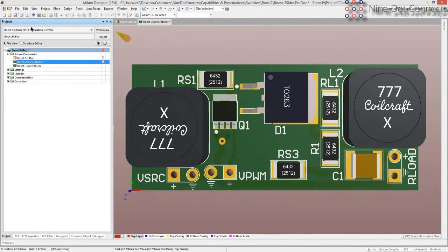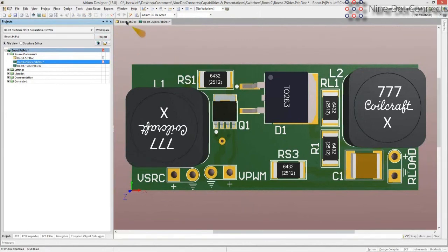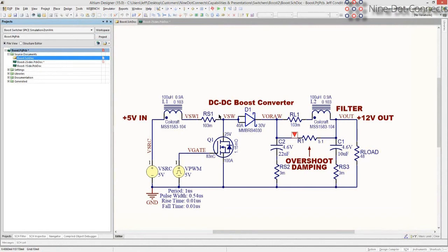In general, I'm trying to get the loops in the same place, so that the switching current flows down one half of the loop and isn't flowing in the other, and then suddenly switches and flows in the other half. I'm trying to get them in the same place. Let's see if I can show that. If you have current constantly flowing out of the inductor and coming in, we have current in this case that will be intermittently going through the diode. It will be constantly flowing through the output and through the input, so these do not matter. But the current is sometimes flowing down through Q1, and the rest of the time, when Q1 is off, it will flow out through Q2 and back down all the way around. The part of the loop that's switching in and out is Q1. The rest of this current remains constant.